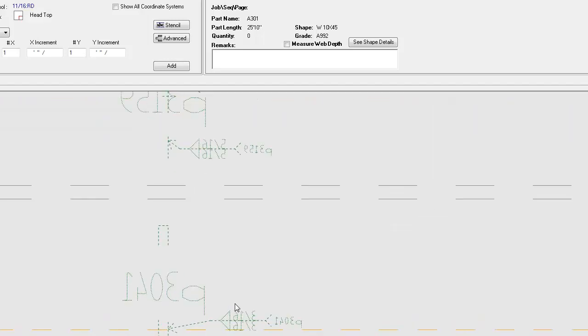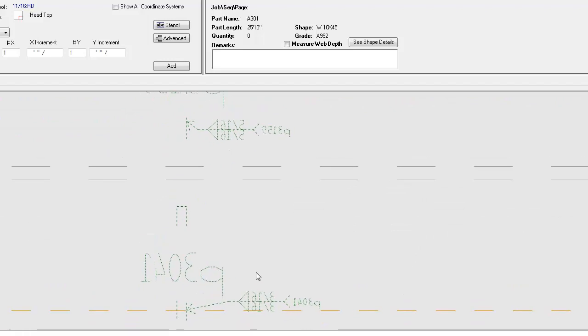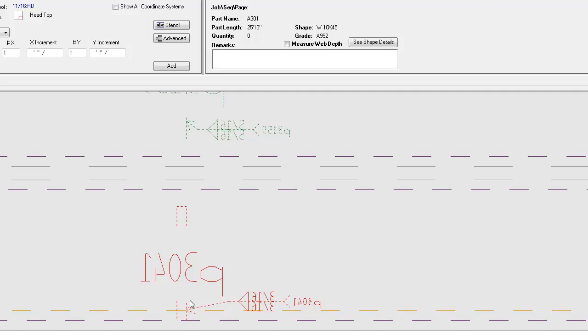So with the current weld information that we're generating, this is not just a simple scribe. It is what we call an intelligent object, because it actually knows what it is and where it relates to on the surface of the material. So this weld information points to the layout mark generated from the assembly. If we try and relocate this weld, it still knows exactly where the assembly layout is the origin.